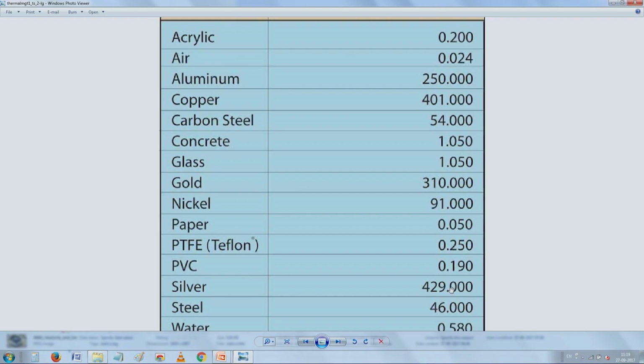So, work is going on about trying to make silicone pads, that is again a proprietary item, by which they have a matrix, a fibrous material which is impregnated with silicone materials, and the whole thing is cured, and then it is available to you in sheets. Those things have very good electrical insulation properties and very good thermal conductivity, with problems which are slightly different in nature.